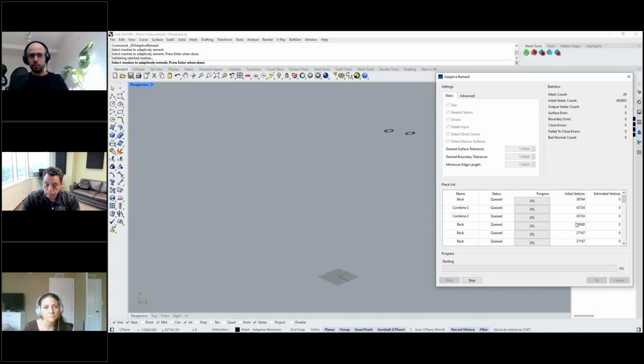40,000 vertices or more. So what this will do is retopologize the mesh, reduce the amount of vertices and polygons that we had initially, and it will also stitch together all the different vertices at the mesh boundaries, so that this creates a mesh that can be used by our software to create the flat pattern. Let's just wait for a couple of seconds until this processes our meshes.